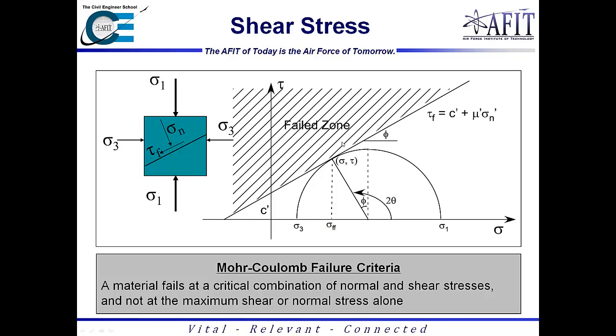So once again, when I was talking about clays having high cohesion but zero friction, with clays, basically you're going to wind up with a slope that looks just like this, coming straight across, and so it basically is a horizontal line, and so you could do a bunch of different circles going across it just for different values for normal stress and shear stress. And then with something like sand, which has no cohesion, you're going to wind up with this line going right through here, and so what it's going to do is it's going to change your friction angle or angle of repose.